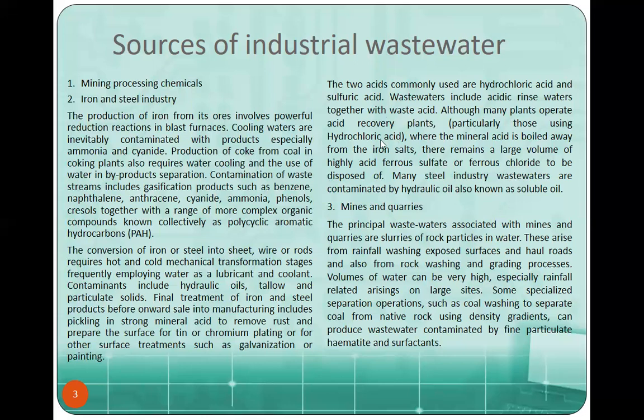Although many plants operate acid recovery plants, particularly those using hydrochloric acid, where the mineral acid is boiled away from the iron salt, there remains a large volume of highly acidic ferrous sulfate or ferrous chloride to be disposed of. Many steel industry wastewaters are contaminated by hydraulic oil, also known as soluble oil. So kaya sa iron and steel industry, yan ang magiging industrial wastewater mo.